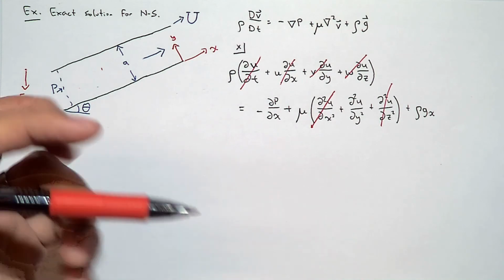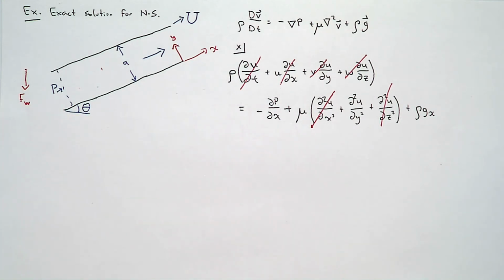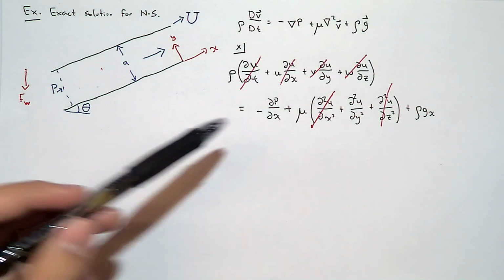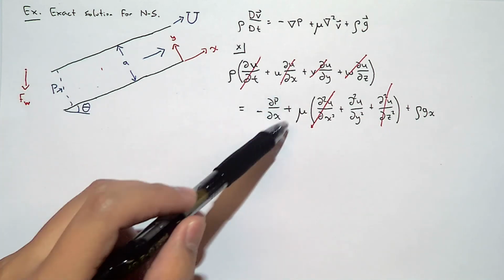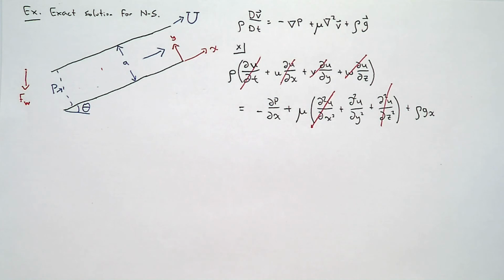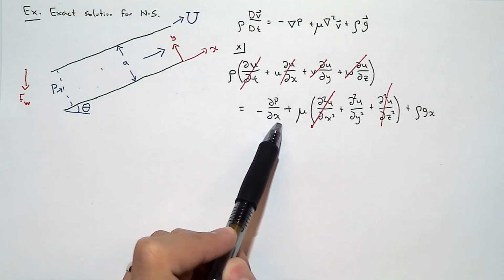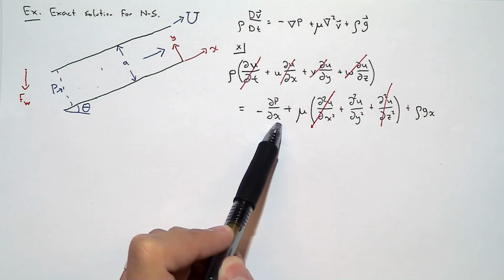We're getting someplace interesting. Let's look at these pressure terms. Do you think the pressure varies with respect to y and with respect to z, this pressure gradient? Remember, fluid always travels from high pressure to low pressure. So if there is no movement in the y direction, there cannot be a pressure variation in the y direction. Okay? So that would mean that this pressure cannot vary in the y direction, right? Or do you think it still varies in the y direction?